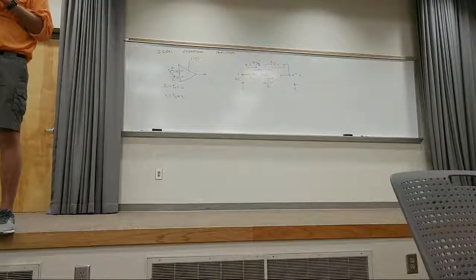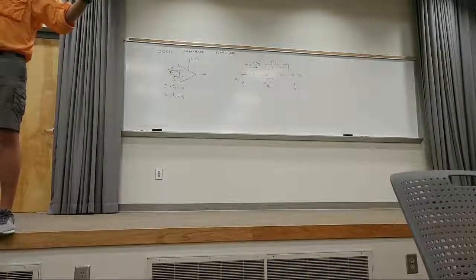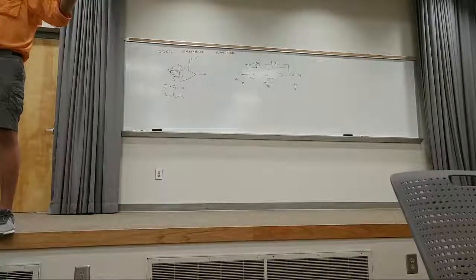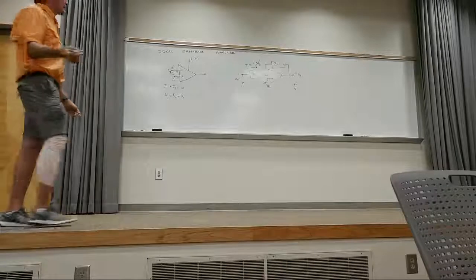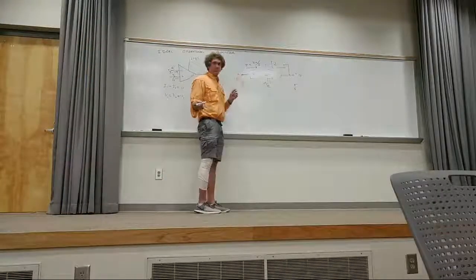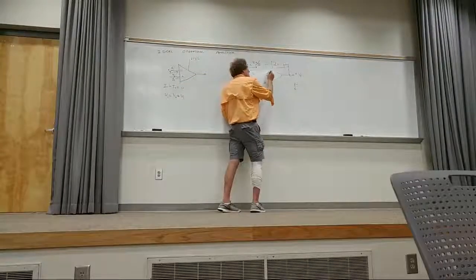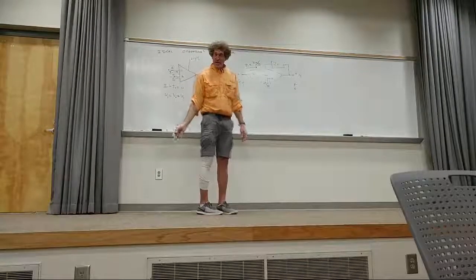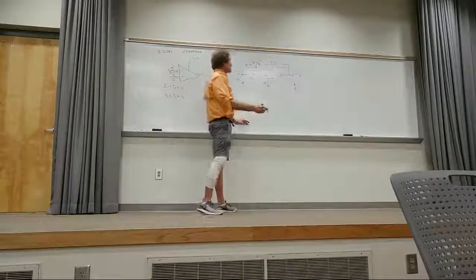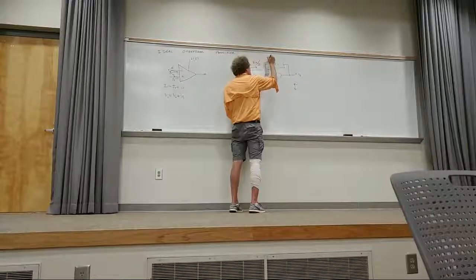If Vn's on one side and 0's on the other, the voltage difference is Vn. Divided by impedance, you have current. It's that easy. Now, that current must flow. It's a reality. I1 will flow if this is a voltage, something other than 0. If it flows, how much of that current can go into the negative terminal? None. All of it flows this way, doesn't it? So therefore, I1 flows here.